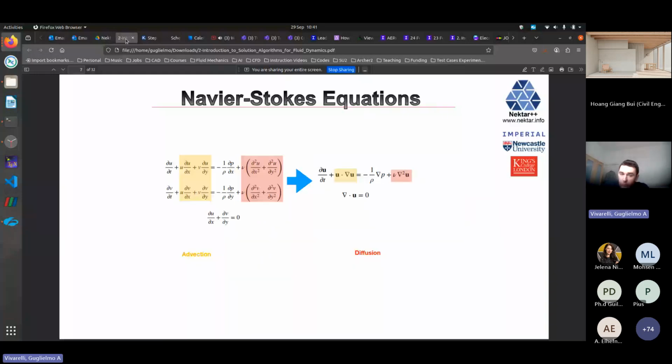So here are the Navier-Stokes equations in incompressible format, and you will note that the first term on the left-hand side only has the velocity terms in the numerator. You've got your convective terms, which are nonlinear in yellow, and then your pressure terms on the right-hand side, and your viscous terms at the end in pink.